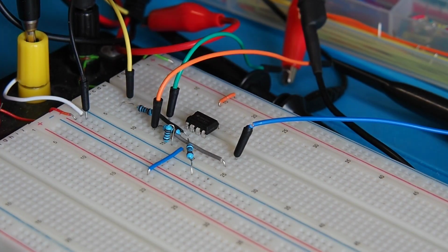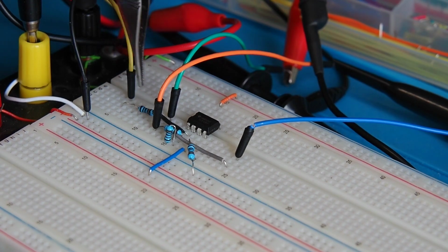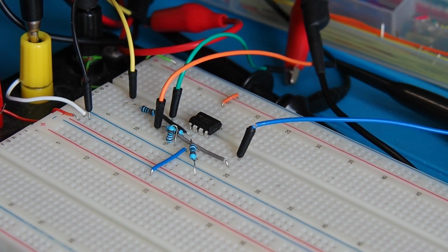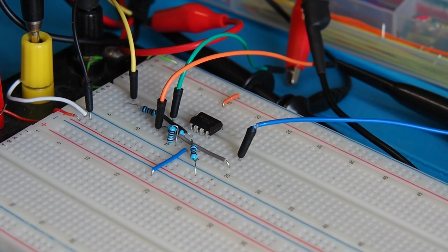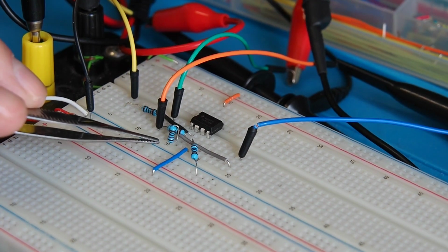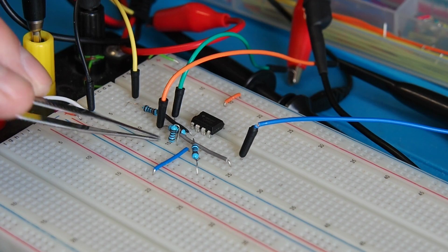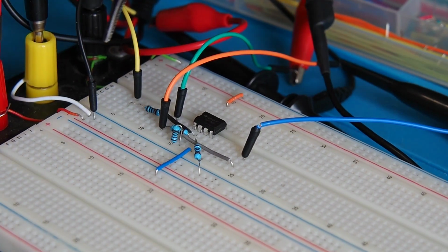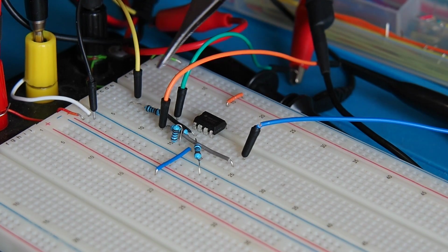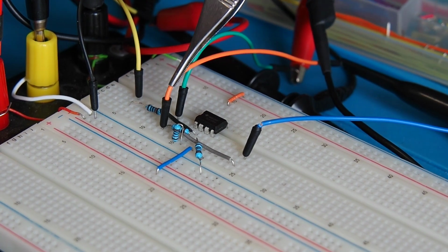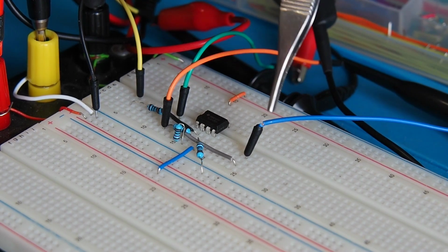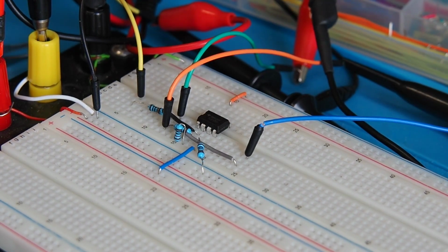Here's the summing amplifier on the breadboard then. Two 10k input resistors are there. I'm just going to do two inputs because I've only got the two-channel signal generator. That's the resistor that is providing the negative feedback, and that's the 1k resistor to ground from the positive going input. So inputs are here on the yellow and here on the orange, and I'm taking the output trace from the blue line there. So let's look at the scope.